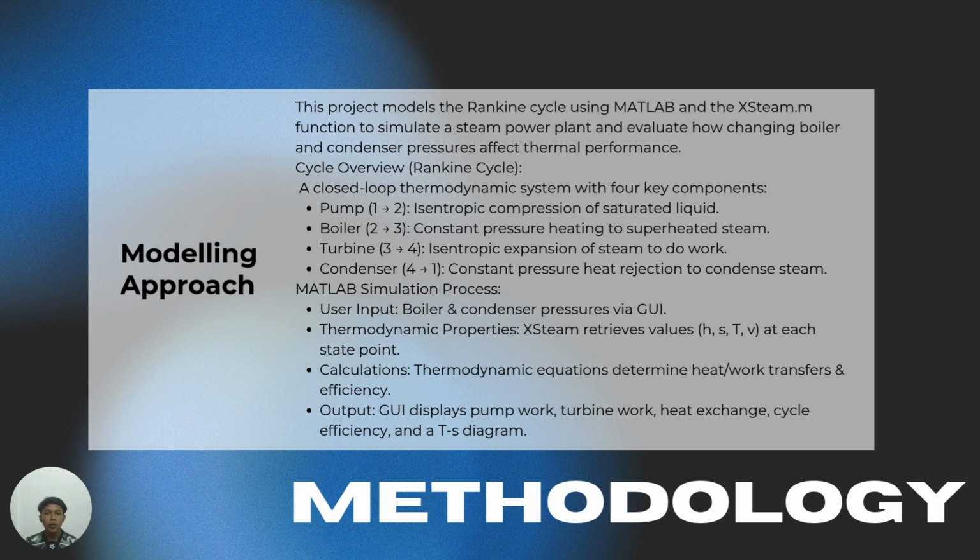This is how the simulation works. The user provides boiler and condenser pressure through a GUI, and then XSteam retrieves enthalpy, entropy, temperature, and specific volume at each key state. Using this data, thermodynamic equations are applied to determine heat input, work output, and efficiency.